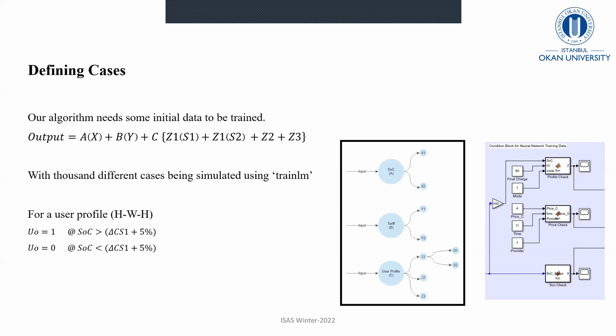For example, if 30% has been used and 70% is remaining, we can use 30% for going back and an additional 5-7% for traffic or route changes, so we still have around 20% to sell back. So we can say, okay, state of charge, tick, it's all right.